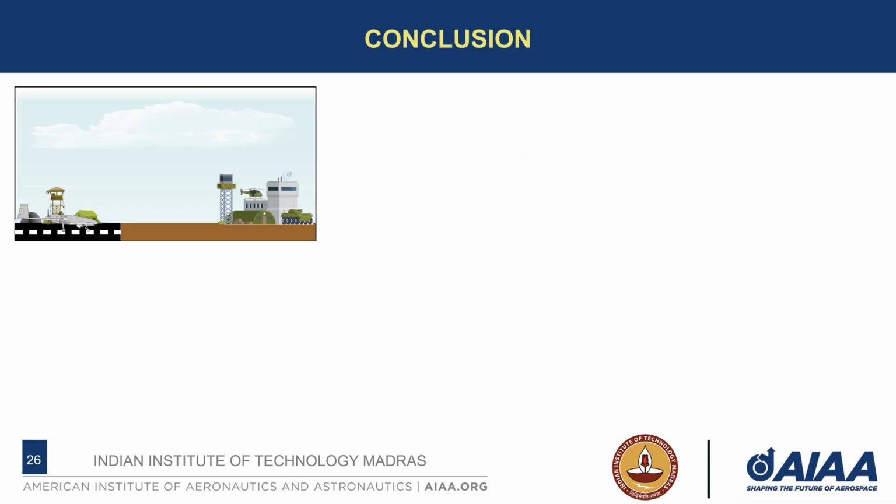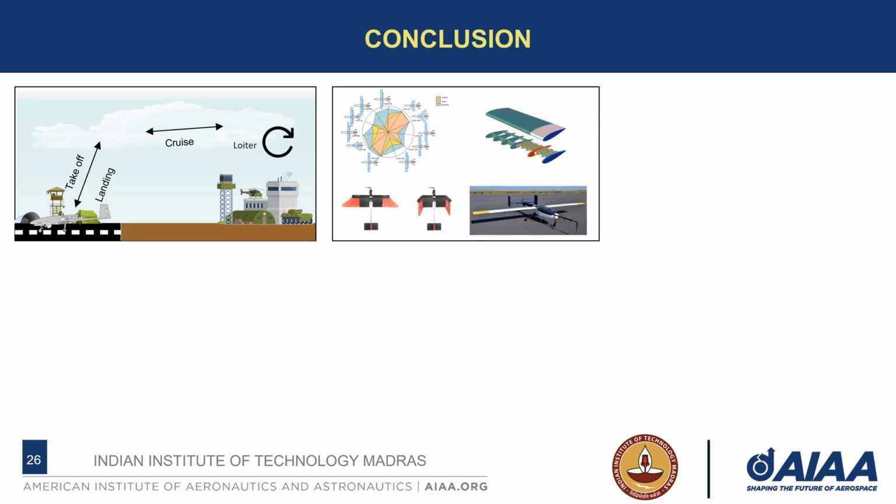So if we want to conclude our work, first we have observed that various mission profiles have their own design requirements, which demand a unique planform optimal geometry. Span morphing is a potential solution which can integrate the benefits of a high-speed, highly maneuverable, low aspect ratio wing along with the appreciable range and optimum fuel consumption of a high aspect ratio wing.